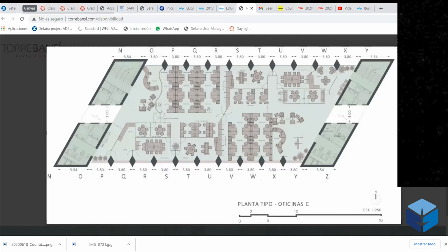Sorry about that. Okay. So what we're going to do is use this plan. And I'm telling you, as if these were 90 degrees angles. What is weird about this plan, and is very efficient in that sense, is that it creates a very narrow distance between one facade and the other. Of course, it's cross ventilation, and it's also, that's right, natural light. Okay, so the shape of this building is helping to achieve both of the most important things regarding a green building: natural light and ventilation, cross ventilation in this case, and it's concentrating the stairs, lifts, and other services on the corners.